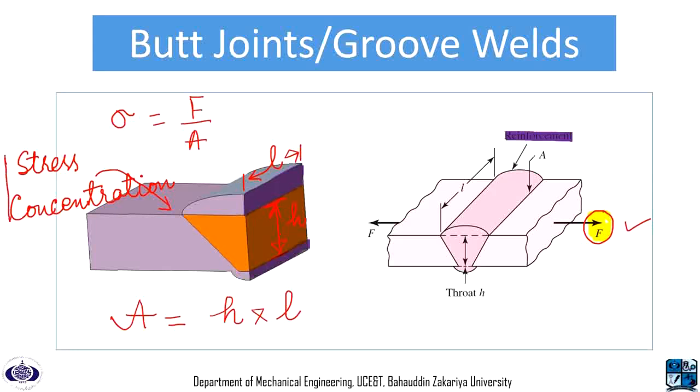So this reinforcement will increase the stress concentration, and that is why it is recommended to remove this reinforcement to avoid any stress concentration.